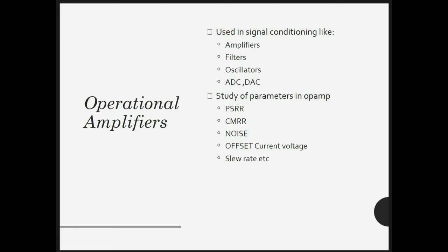An op-amp is used in a vast array of consumer, industrial and scientific devices. Op-amps may be packaged as components or used as elements of more complex integrated circuits. The output voltage signal from an operational amplifier is the difference between the signals being applied to its two individual inputs. In other words, an op-amp output signal is the difference between two input signals, as the input stage of an operational amplifier is in fact a differential amplifier. So we will now look at the structure and the operation of the differential amplifier.